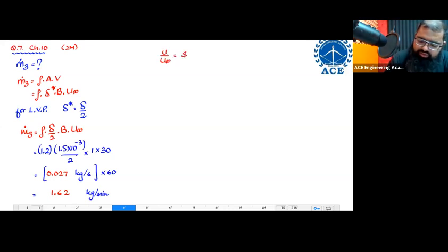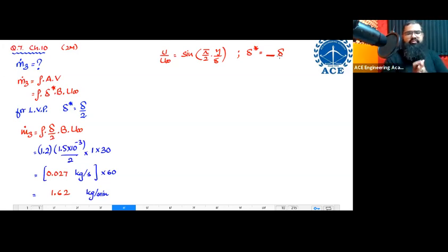Let us take one question. He will give you, for example, u upon u infinity equal to sine of pi by 2 into y by delta. Get me the value of delta star here. Delta star is equal to something times delta. Please find out this particular value.